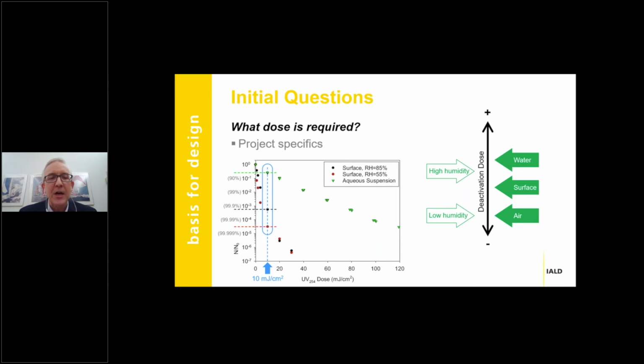If you're inclined to delve into research reports to ascertain what dose might be appropriate for a given pathogen and level of disinfection, be sure to note the wavelengths used in the study and whether the study relates to airborne pathogens, high or low humidity conditions, surface disinfection, or deactivating pathogens in solution, so you can assess if and how the findings relate to your application. Otherwise, again, you might need to lean on your manufacturer for guidance.